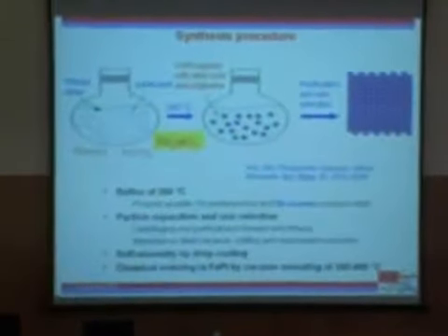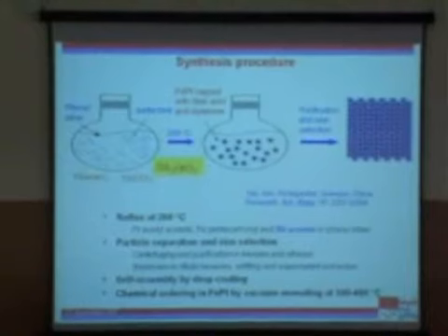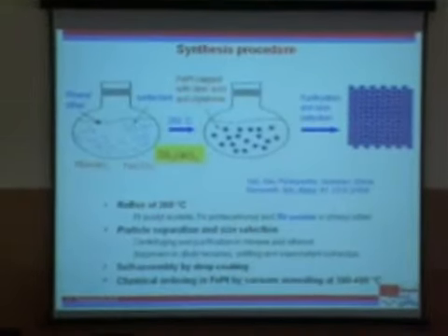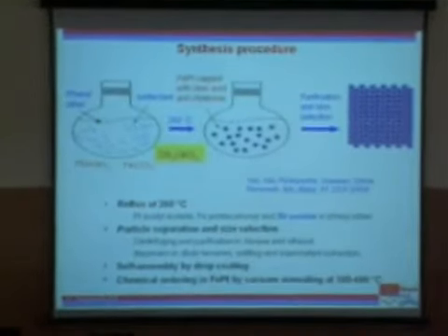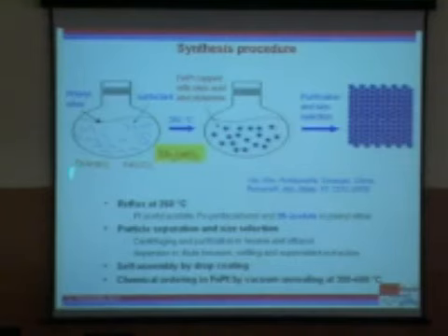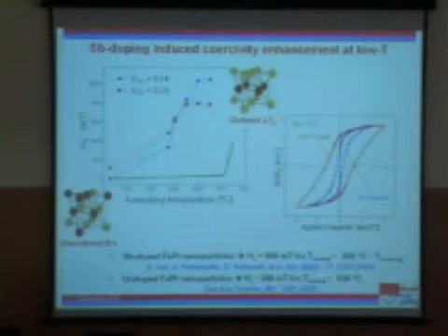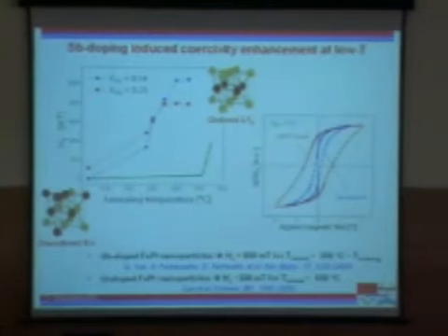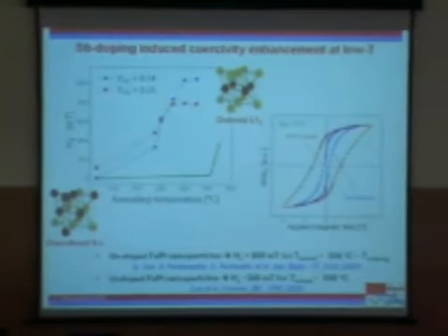So we took a couple of approaches, one not very successful and one extremely successful. I want to just share both of those with you. I won't bother you with the details of the chemistry here. Just want to say that we take platinum and iron, and we just put in this additional element, antimony. The idea was to get the ordering, or the crystal structure, that gives the high coercivity phase at a lower temperature, so that we don't go to high temperatures which would destroy the architecture.